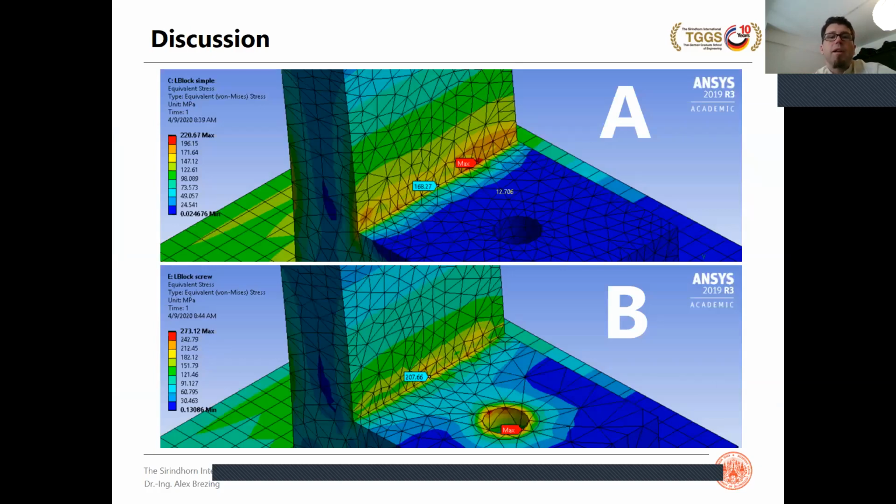So if you compare them again, in model B you have a higher stress level, but just slightly higher. You could even say, on model A the maximum stress nominally is around 220 megapascal, and on the lower edge it's possibly around 220, so it's almost the same. So I believe if you run both simulations with a really fine mesh, you would probably get the same stress level.